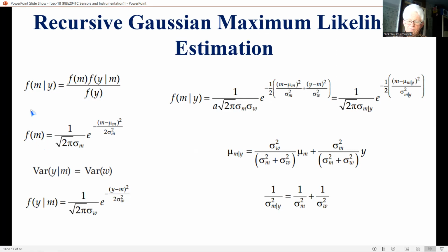So y of quantity m, which is estimated. The data y has both model error sigma L, also denoted by sigma y, which corresponds to the error in the model that is used to represent m and/or unknown disturbances that affect the true value of m, and measurement error sigma with the sub w. Sigma m and sigma w are also given. We need to determine an estimate m hat of m.